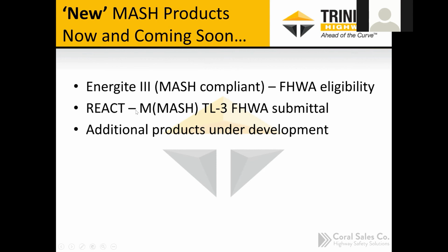The React M, we call it, which is the React MASH system. If you've seen the black cylinders that are approximately 36-inch wide, roughly, I believe, 54 inches tall, those cylinders are common in the Puget Sound area. Actually common over here in the Spokane area of Washington as well. California uses a lot of the React system, and they're a low maintenance system. We are just submitting to the FHWA. We've completed all our crash testing and are in the process of seeking FHWA approval, and we'll be coming to the states for approval of that product very soon as well.